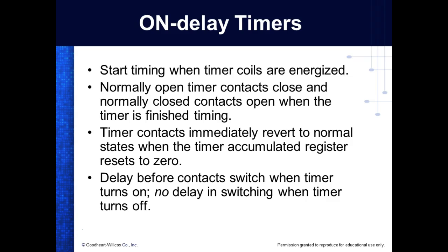Timer contacts: normally open contacts close, and normally closed contacts open, when the timer is finished. Timer contacts immediately revert to their normal state when the timer accumulator register resets to 0. Now, this is definitely PLCs. Those other timers don't have accumulator registers. They either have diaphragms that push a liquid from one side to the other, or a synchronous motor that runs in synchronization with it, or solid state devices that generate our time.